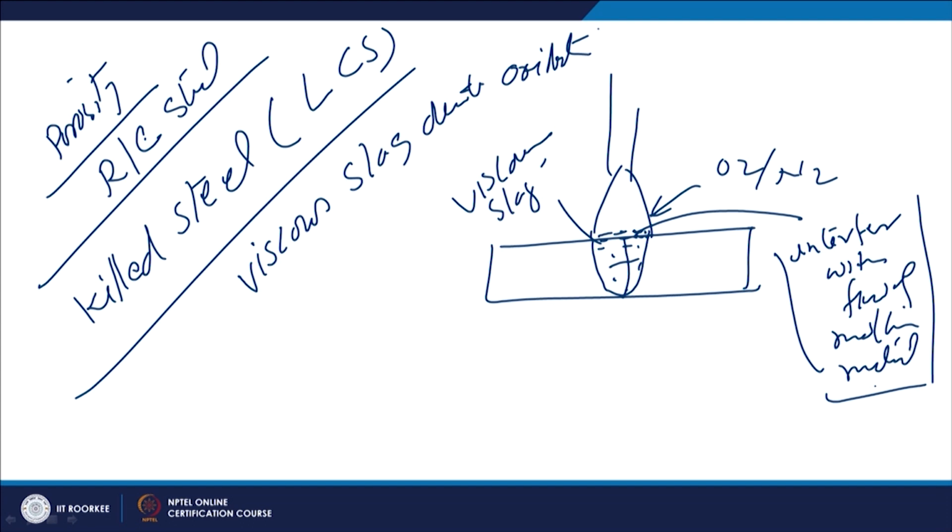of the molten metal. So, in order to take care of this, there are means to avoid the formation of the viscous slag or the oxides of high viscosity adversely affecting the flowability of the molten metal. There are two things which are tried. One is to have very effective shielding of